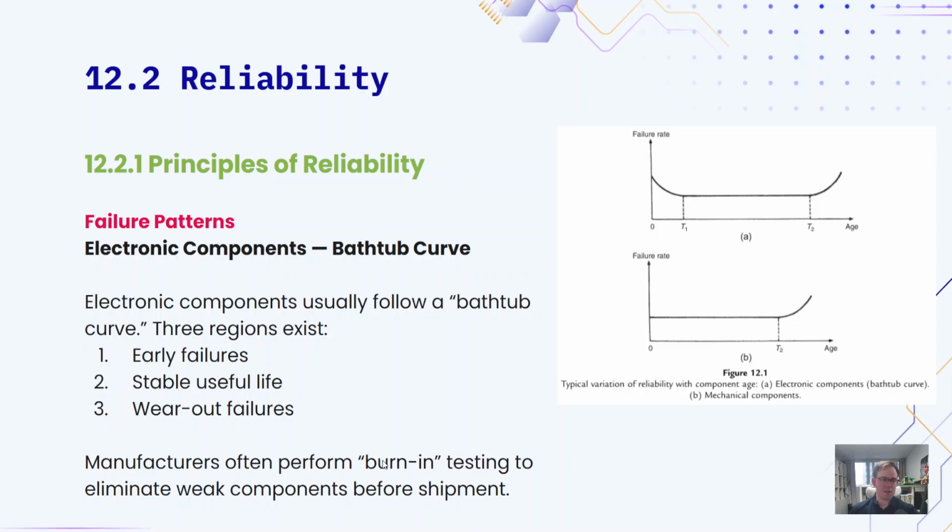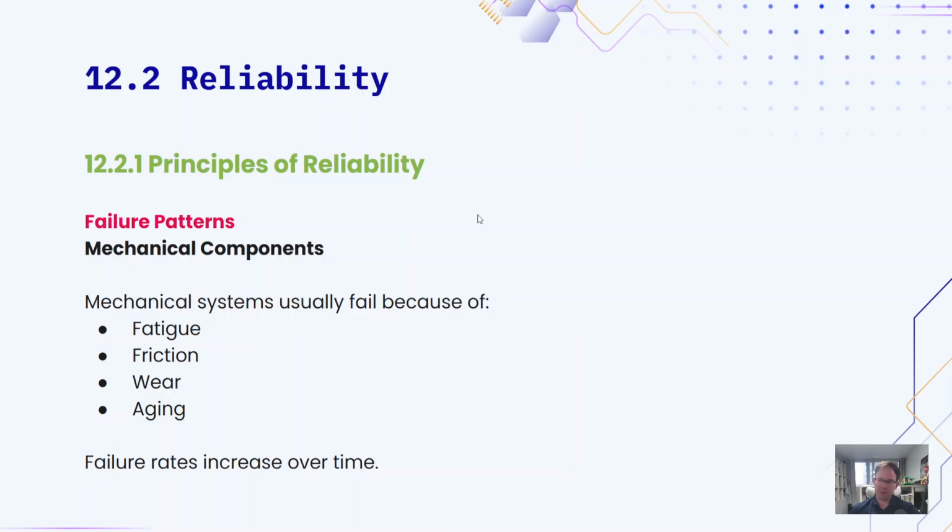Yeah, that's true. They do that with semiconductors too. They test semiconductors before sending them out so that all of the bad chips that are going to have failures at the beginning, they just get rid of those before they put them on the market. So then you can produce this kind of curve. You reduce the early failures or effectively eliminate the early failures. So everybody who buys your product is pretty much happy with it. This is a really good way to sell products, not 100% of the products that come off the production line are going to be stable. So you get rid of the unstable components first and then just only sell the good components. So then everybody's happy. You can get high reviews.